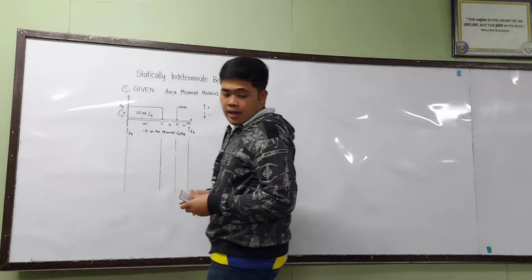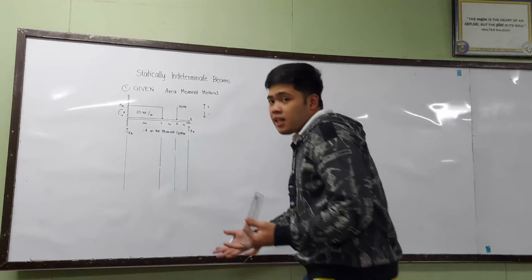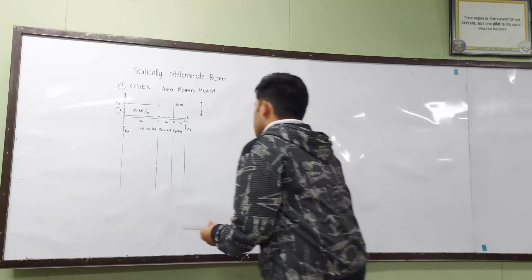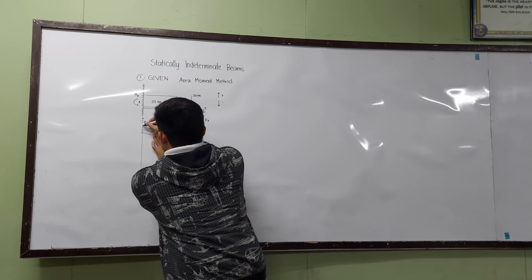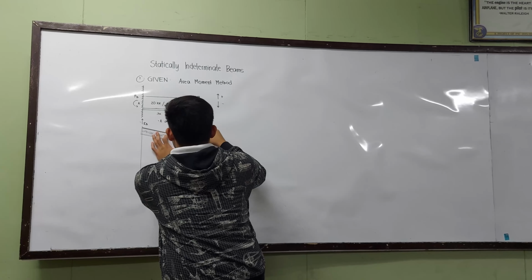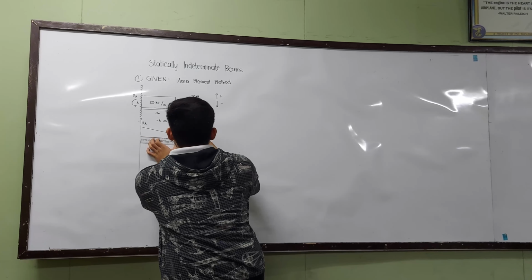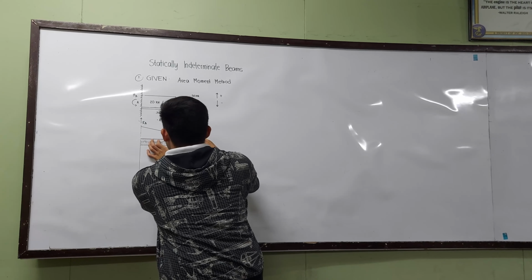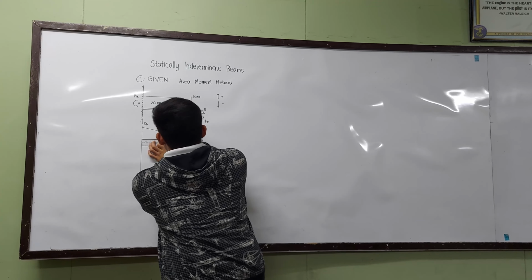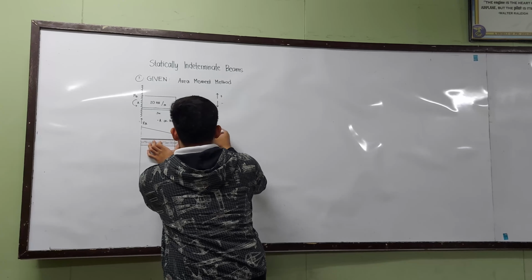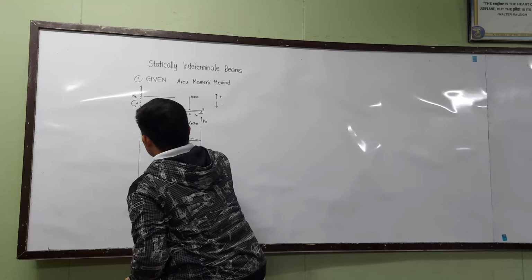So, let's draw an inclined triangle to visualize in our diagram. The inclined triangle that goes upwards with respect to our moment center goes along the point B, and it is positive.